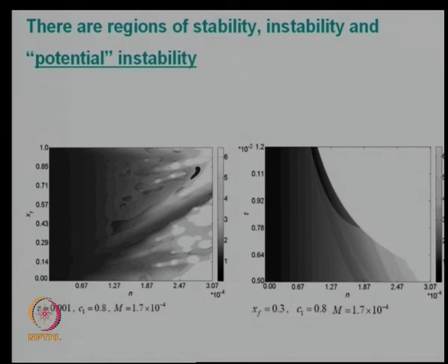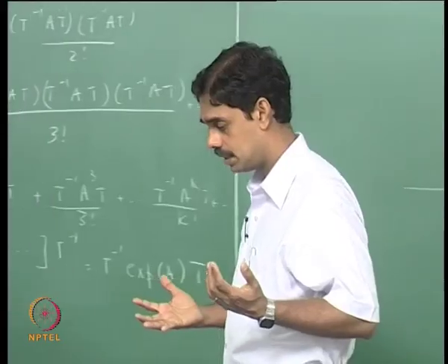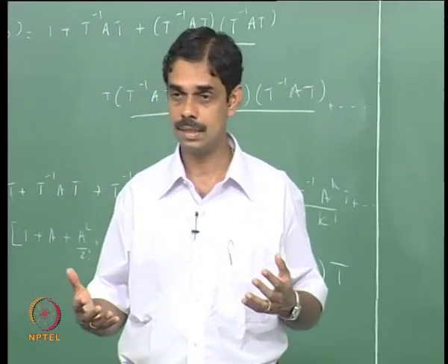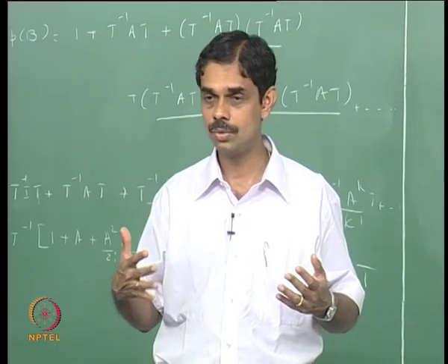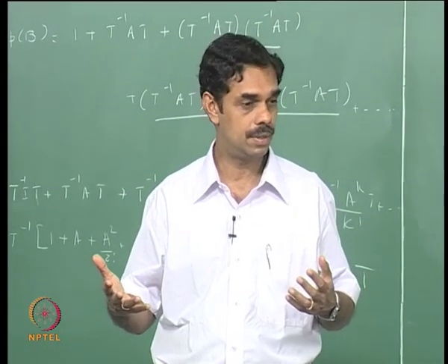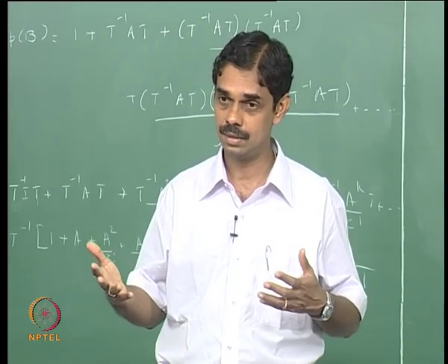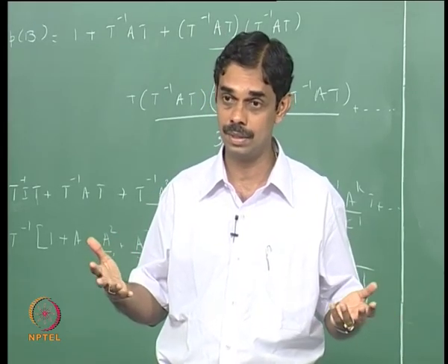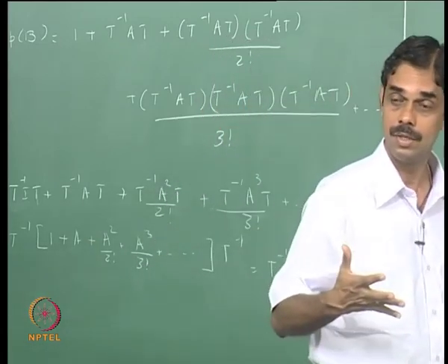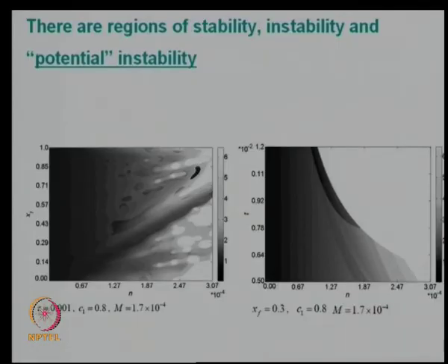Now, location of the flame, XF. Shouldn't it be some skewed kind of? Yeah, so not only does the amount of acoustic driving depend on the n and tau or the heat release rate, but Q is a function of U, and then U and P are also related, and what you want is the phase between Q and P. So let me explain this.